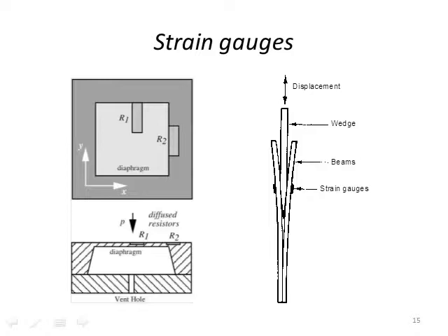So when you have a finite change of pressure between the top, you see with P, and underneath the diaphragm, this diaphragm will deflect, and then these sensors, the resistance, which you're monitoring in real time with a microprocessor that's connected directly on the same silicon chip, will give you a function of how much this diaphragm is displacing.